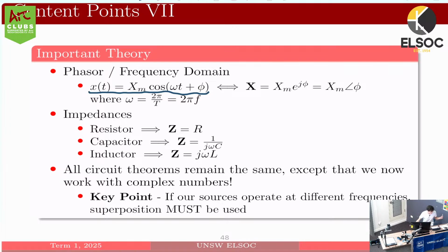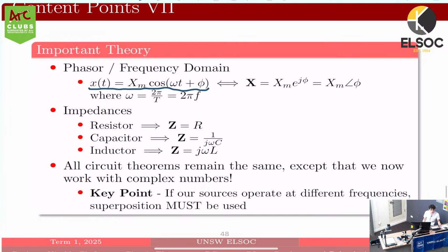Yep, that's right. One issue that we'll find is that trying to work with sinusoidal signals in our circuit as is is really difficult because they're expressed in the time domain. And so one issue we'll have is that if we're working with something like inductors, so we've got L di/dt, we start working with differential equations. And that becomes really, really difficult.